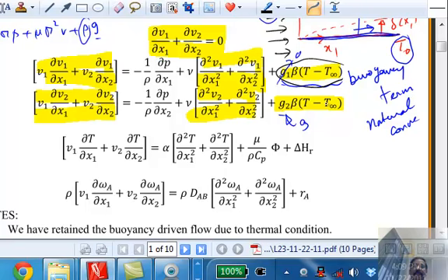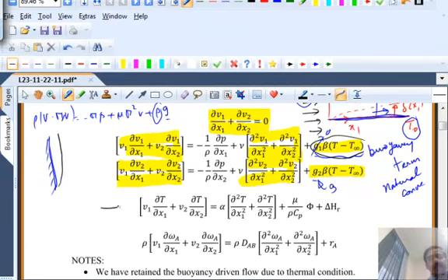And the next equation is the energy balance equation, where the left-hand side is what? Is the convective term. Whenever you have velocity, the velocity carries energy with it. So that's a convective term. The right-hand side, the first term is the conduction term. What is this term? The third term. Viscous heating, viscous dissipation, heat generation. What would be the last term?